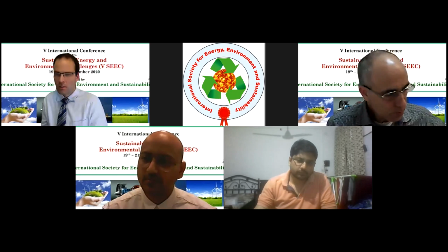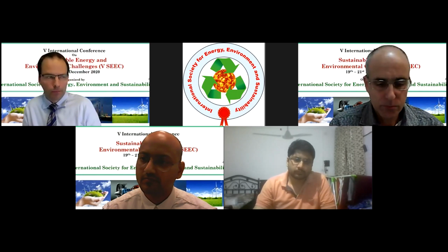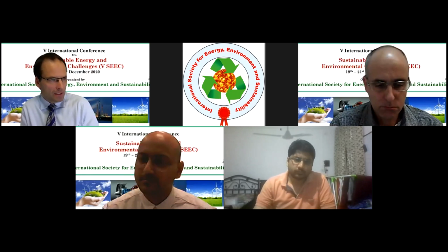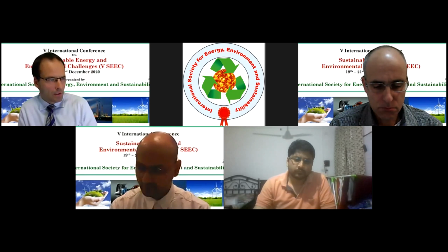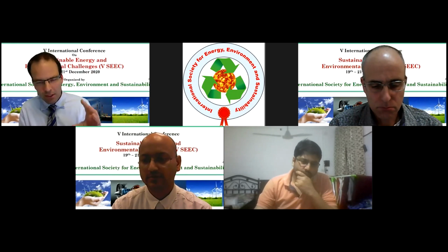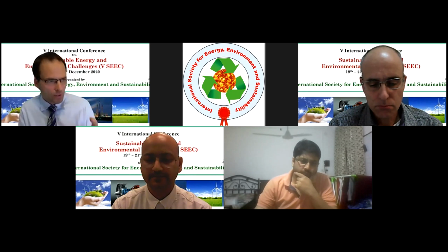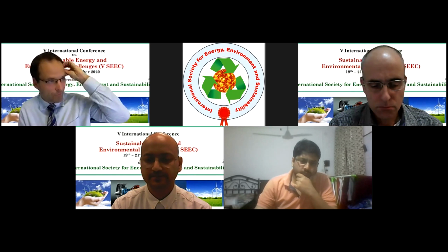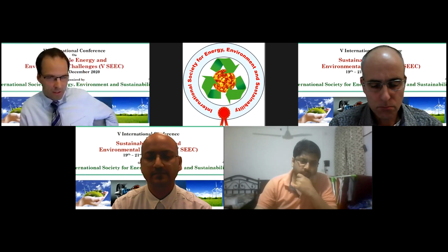So these nanoparticles, you can dope metal nanoparticles in an LIG in two ways. One is to have the metal salt in the substrate, and then during the laser process, the lasing can also reduce that metal salt into the metal, and the nanoparticles are just embedded in the graphene.